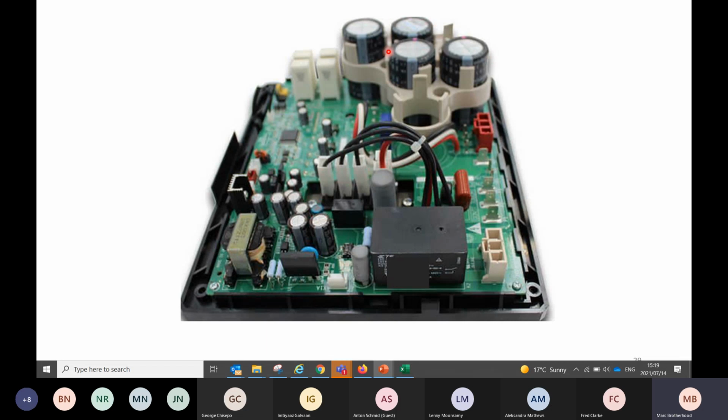These are the capacitors that supply work. They don't supply the transformer, they supply the compressor or the motor to turn the pump. Here's a little bridge rectifier I showed you earlier on. Here's a switch mode power supply. You see all these caps, they're supplying about 8 or 9 different voltages. I said earlier in the training, if you look at just this little section, this is my switch mode power supply built into my power electronics.